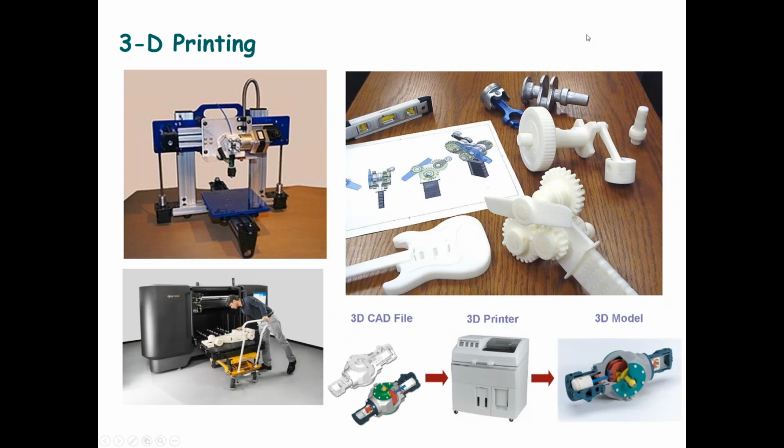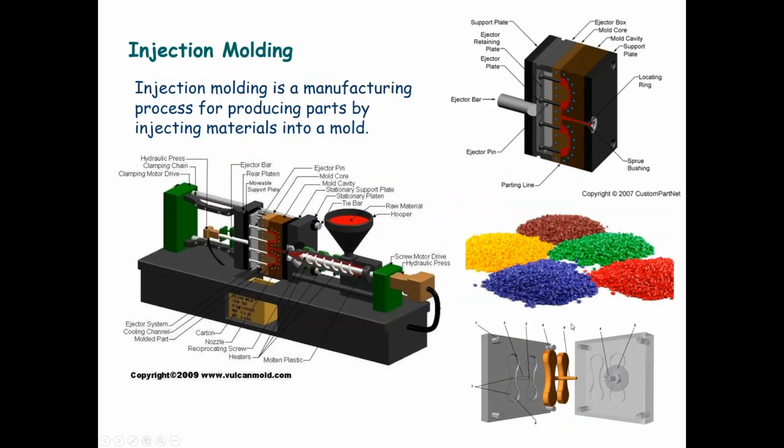In fact, 3D printing can be accessed through photopolymerization, viscous solution printing, or in general, as in most devices, by extrusion. It's essentially an extrusion of a filament or a pellet through a heated head coupled with a CNC machine or a programmable machine that's capable of printing or extruding the material.